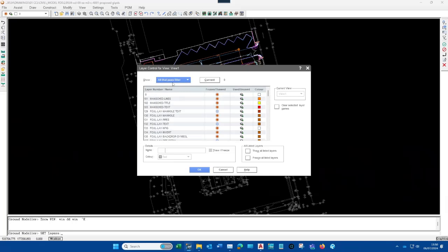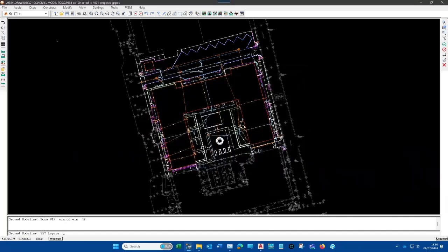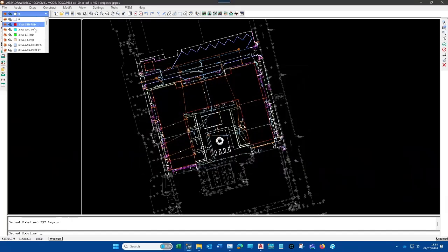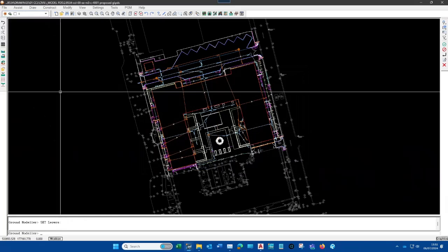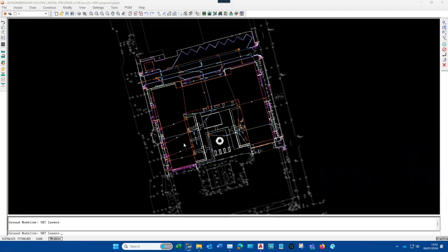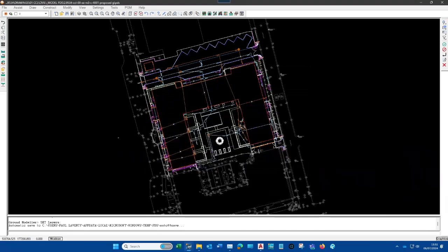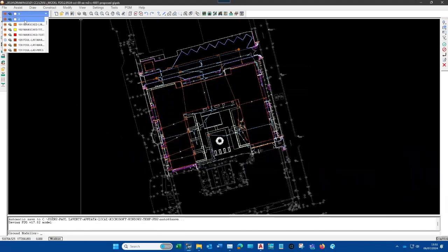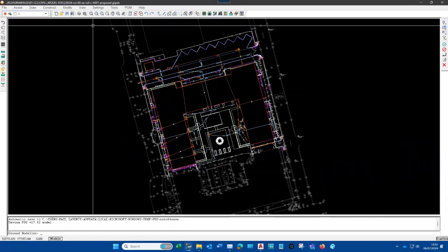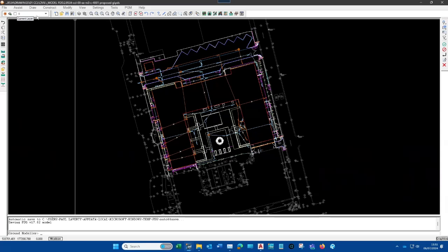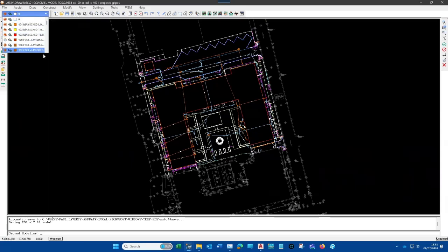There you can use the filters, and really quickly, if I go unused, so you've got 0, 1, 2, 3, 4. If I go OK, and go to this pull down menu, 0, 1, 2, 3, 4, 5, because that's the filter that we have applied. Go back to the stack of papers, which is the layer. If I choose all in use, first one is 100, 1 jumps to 129, go OK. This is 0, 100, 129. So the filter that you applied by going into this layers, the stack of papers, gets applied to the layer drop down menu.